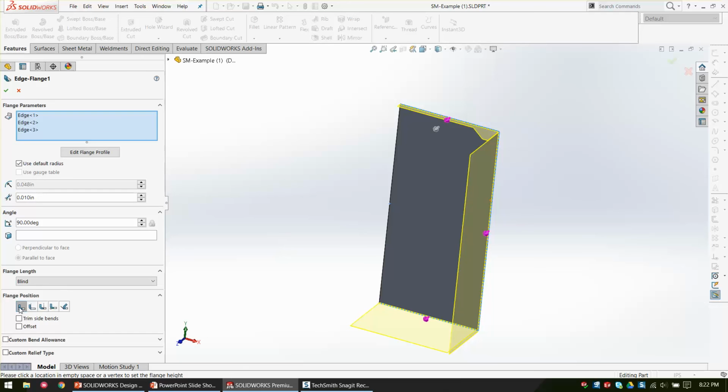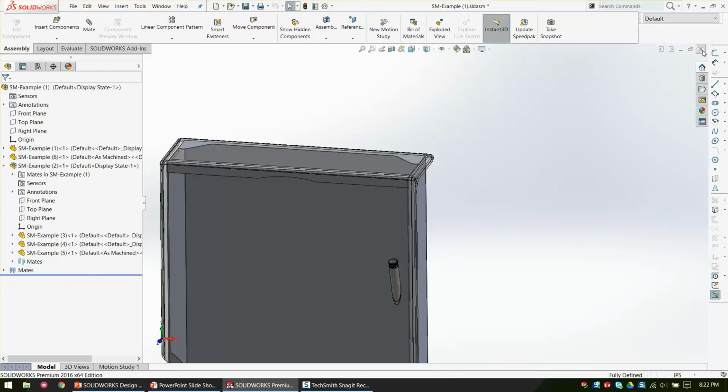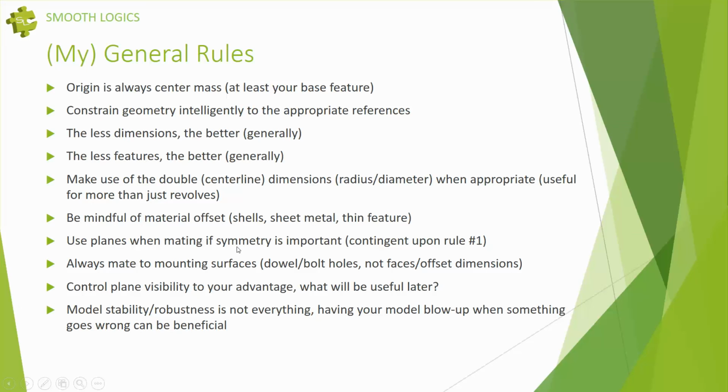I know the sheet metal thickness, the gauge, is likely to change. So I'm going to construct my models around my known dimensions that I want to keep, and the material can do whatever the material wants to do. Make sense? Any questions? All right. I have a couple doozy examples at the end here.